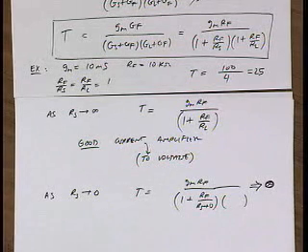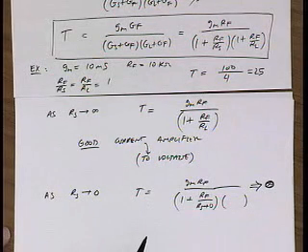And this is obvious, right? If you voltage drive the input, any current feedback is not going to have any effect on the input, let's say VBE or VGS or V pi, and so the feedback becomes ineffective. So to have good performance, we definitely want to drive it with high source impedance. Questions?